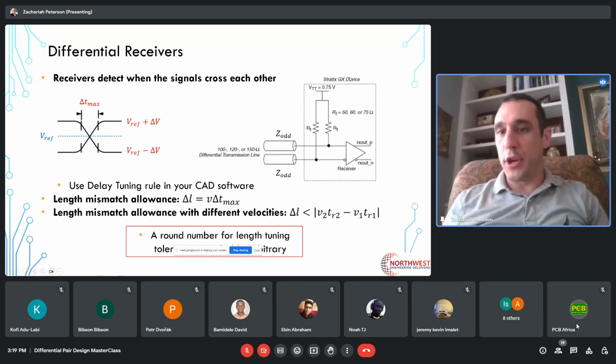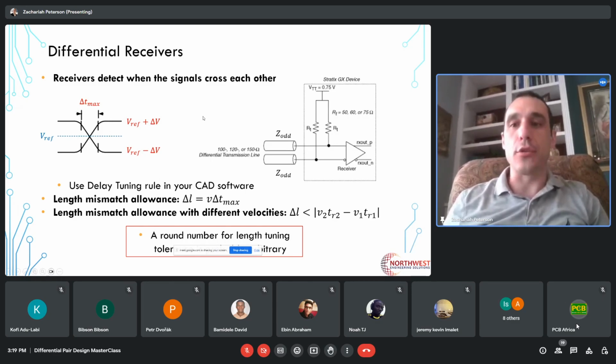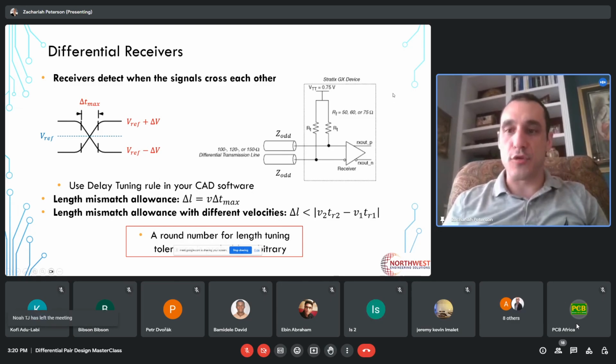But you'll notice that this is for a Stratix device, so an FPGA. So a lot of FPGAs will have these different termination circuits built into different IOs. And you're basically programming all of that when you create the image for your FPGA.